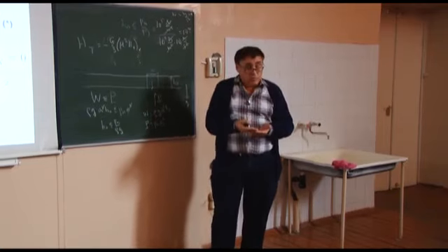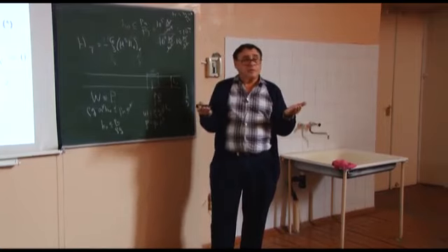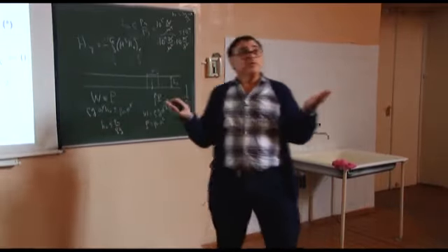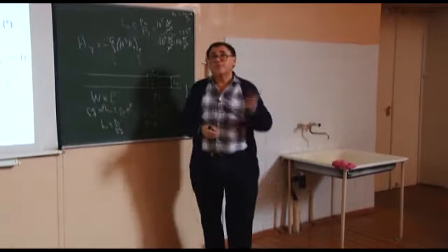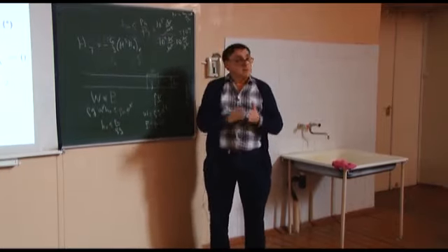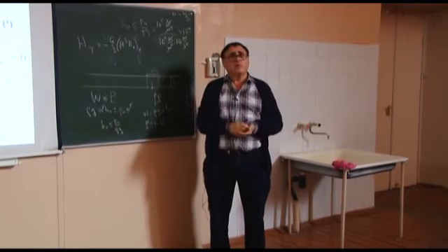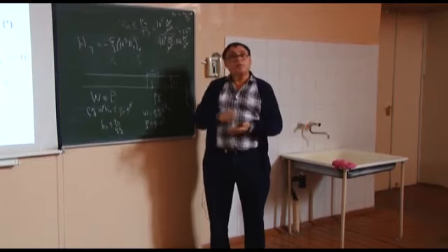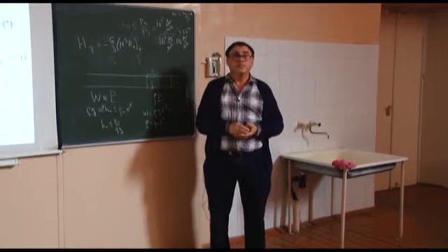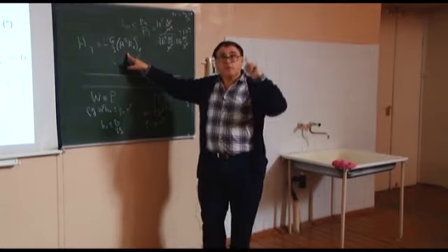And the answer is no. There is no way to know, even after maybe 3 advanced courses in heat transfer, it's impossible to know what the temperature distribution was 5,000 years ago. Not 5,000 years ago, 5 seconds ago. It's a mathematically ill-posed problem. It's impossible to solve. There are some reasons, I don't want to discuss them, but there are some simple arguments why not. So this is a nonlinear heat equation, but a backward diffusion equation.